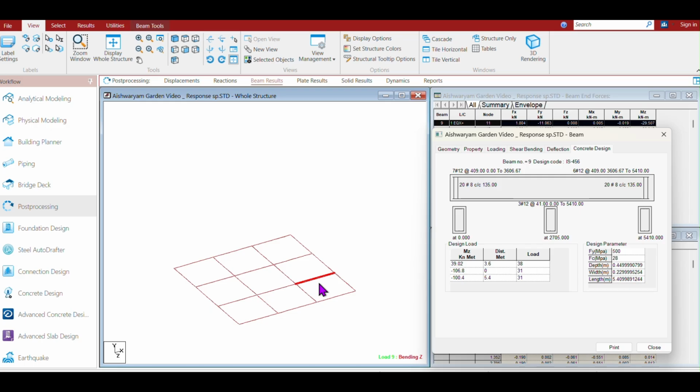But it is not required to provide the same thing. If you are required to provide 2 layers, then you can change the reinforcement percentage in the midspan. But in general, the midspan reinforcement may also be required to be equal to the reinforcement on the upper side. That is better for the safety of the building.